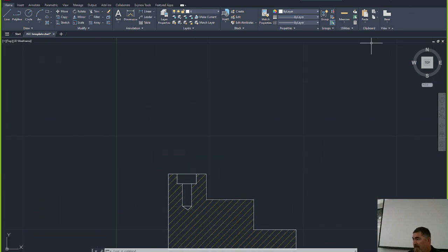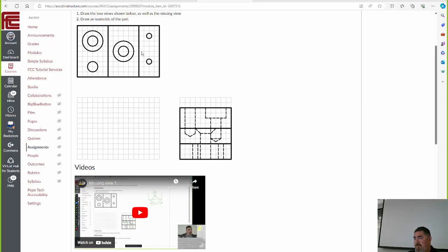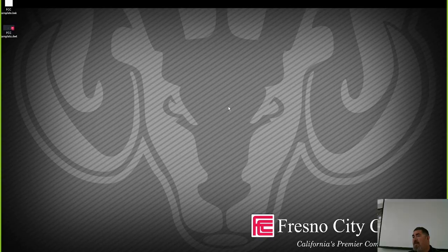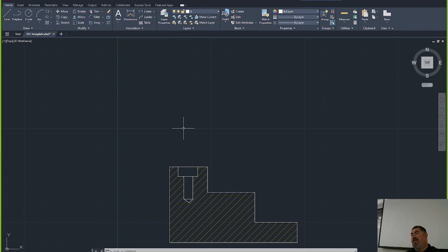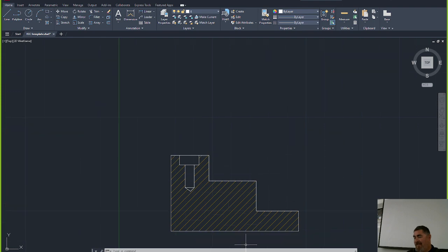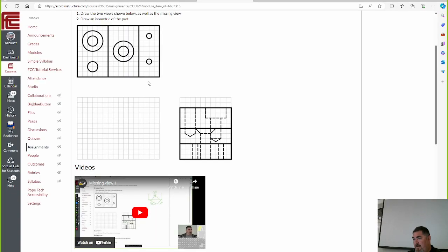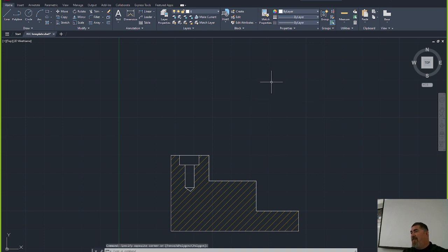On the top view, what do I need? So what was that green line? What's that called? Cutting plane line. So the line that goes through here, showing me where I'm cutting, that's the cutting plane line. What kind of line is that supposed to be? Thick line. What line type is it? What kind of dashes? Phantom. It could be either phantom lines or bigger hidden line dashes.